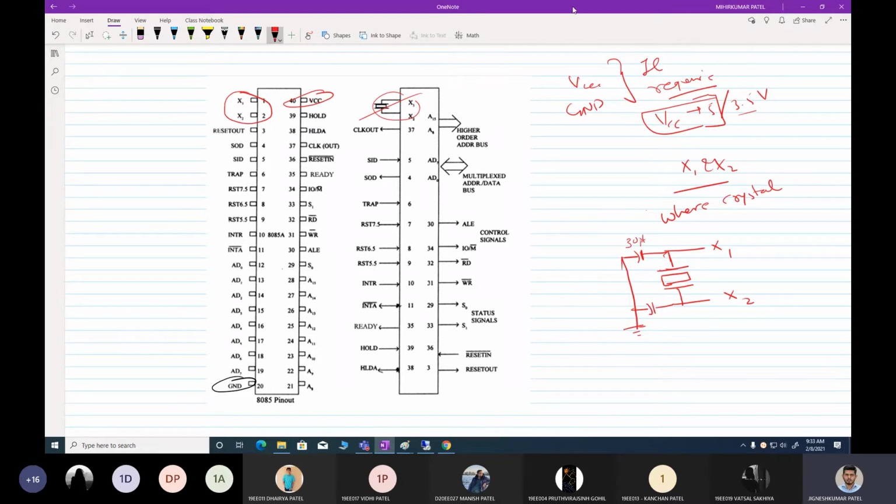For 8085, it is not at all mandatory that you know how to connect a crystal. For 8051, we will see how to connect a crystal. It can be as simple as an examination question. But for 8085, we will be providing less focus. That's why this is not so important. But this is how it is connected. So X1 and X2 are the pins which connect a crystal.